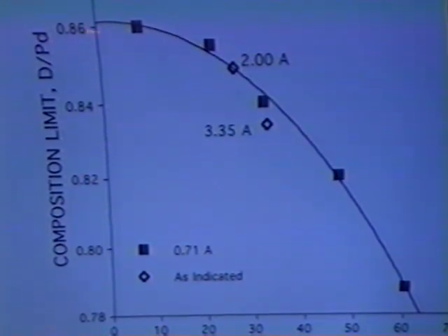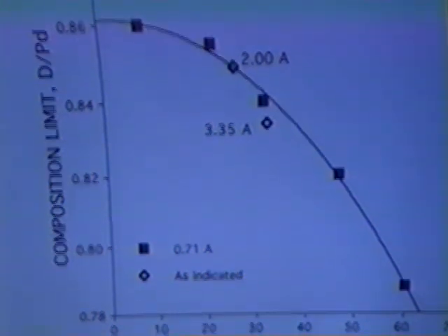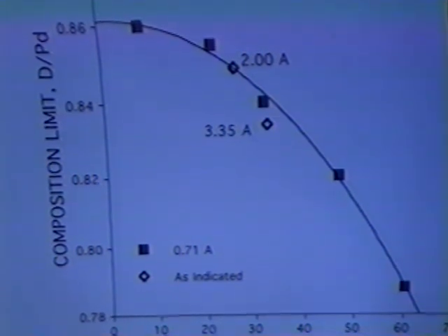Let's see, the composition limit is temperature dependent, as we all know. This just shows the relationship between the composition and the electrolytic temperature, and that's the primary variable. These are done at two different currents, but if you plot it in terms of temperature, it makes sense, but it doesn't make sense if you plot it in terms of the current itself. So temperature is far more important than current, but when you change the current, you automatically change the temperature, and that's what you're primarily seeing.